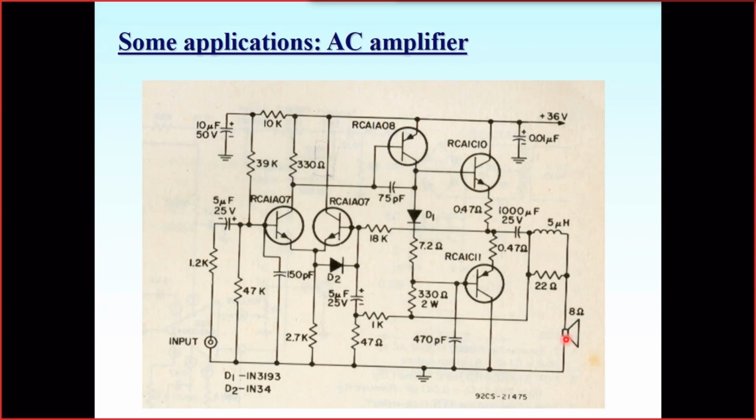You need to think not just about the general principles of how you get amplification using a transistor, but also because you have to stabilize the transistor operating mode, to have constant biases for the base current, so that all the regimes and all the parameters of the transistor are as stable as possible. This requires including different kinds of temperature drift compensation circuitry, gain drift compensation circuitry, and so on.